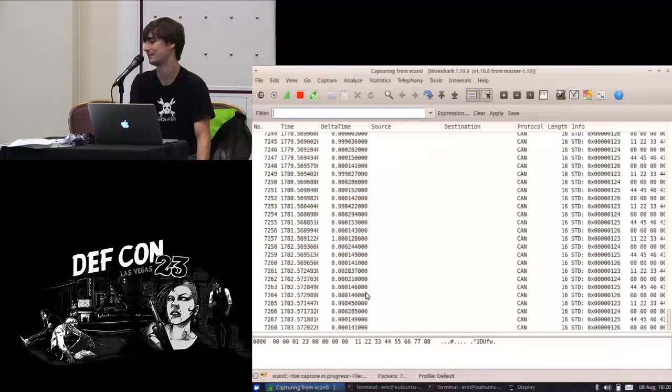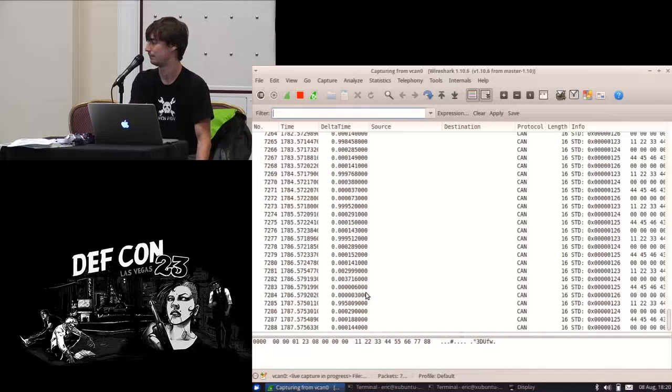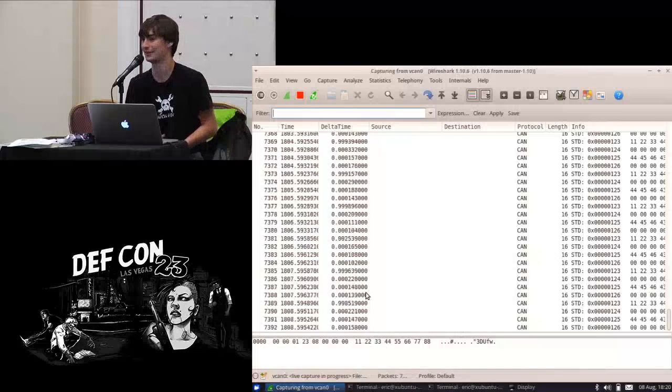So all this stuff, it's pretty low-level tools. It's more meant for the development end, but it makes it pretty easy to then write your own software using CAN. And if you do C right now and you do network devices or any kind of socket stuff, extending that to CAN has just become, okay, I'll call it with the right flags, and that's about it. So that's pretty much my really quick tour of SocketCAN.